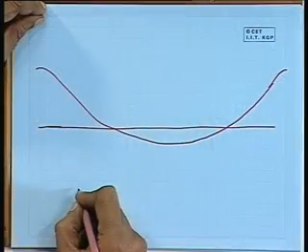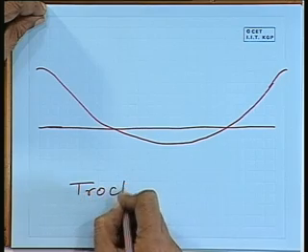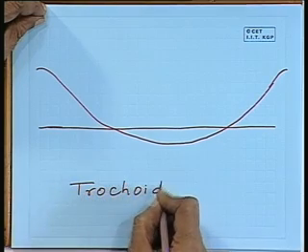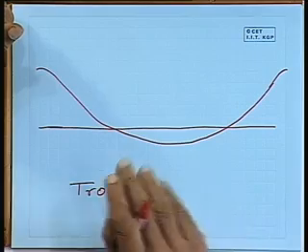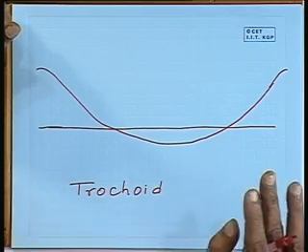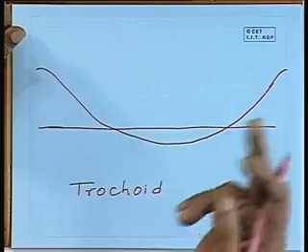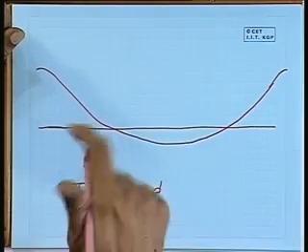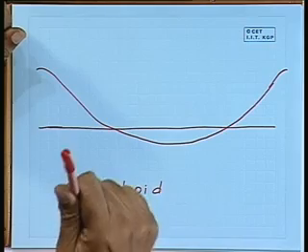Now, the mathematicians will try to tell you where you get this type of a curve, which is mathematical. So, it is a trochoid, and we say it is a trochoidal wave. What is a trochoid? A trochoid is basically you take a circle and on the circle you take one of the radii, draw a radius, on that you fix a point which is half the wave height and rotate this along a flat surface.